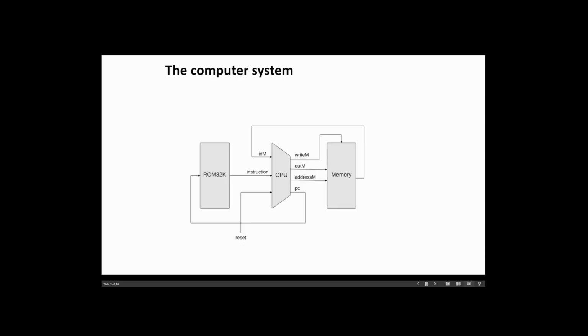This diagram was used to implement the Hack computer in one of the tasks that we have done previously. Here it can be seen that the CPU takes its instruction input from the instruction memory and also takes the value of the selected data memory register as one of its inputs. The reset input is a value that tells whether we bring the CPU back to its initial state, or to be specific, to start the operation of the CPU all over again.